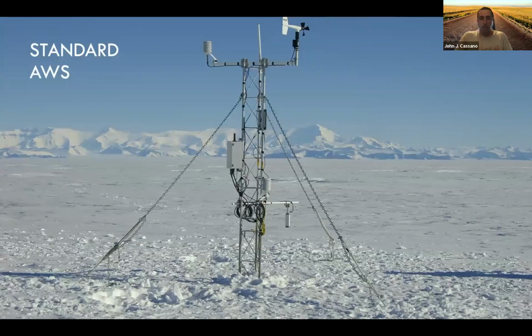And the standard weather stations that we install and maintain across the continent look like this. It's a 3 or 4 meter tall tower. It has sensors on the top to measure temperature and humidity. Oftentimes it'll measure temperature at least, and possibly humidity at a second level. There'll be a wind vane that measures wind speed and direction. There's an electronics enclosure that has the computer that logs the data. There's a communication system there that allows the weather station to transmit data either by radio or via satellite. And then there's a pressure sensor in here that logs pressure data.